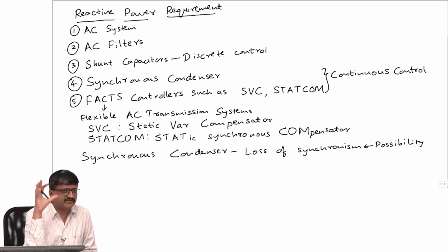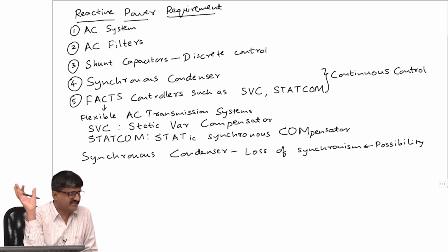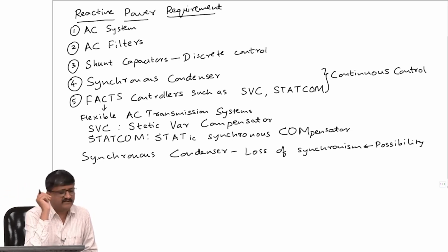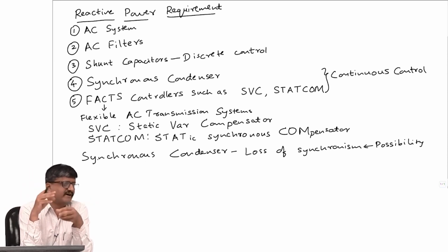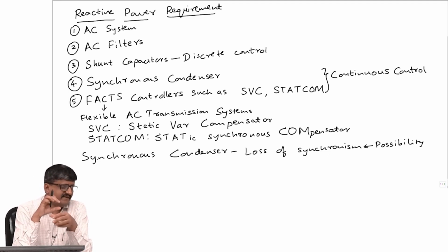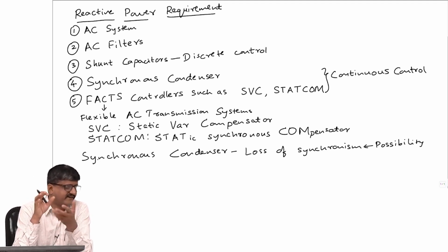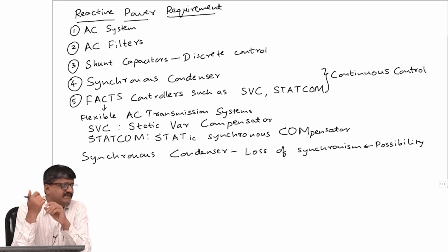The external DC source is stationary equipment, and the field winding is rotating. To connect them, you need slip ring brushes. Whenever there is contact between the rotating slip rings and the stationary brushes, there will be wear and tear, so you need to keep replacing them periodically.